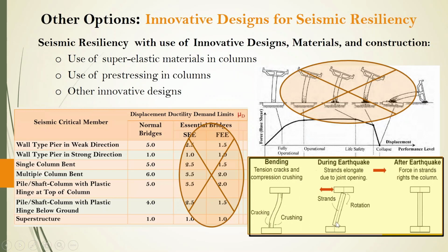We are looking at the rocking option, which is actually more suited to precast columns and ABC. So we go through this rocking, but after the earthquake it comes back to the original position. So basically we are able to use the bridge after the earthquake for service condition and functionality. As compared to this one, we are not going through post-earthquake yielding and eventual failure, but we are remaining within the range where bridges are usable.